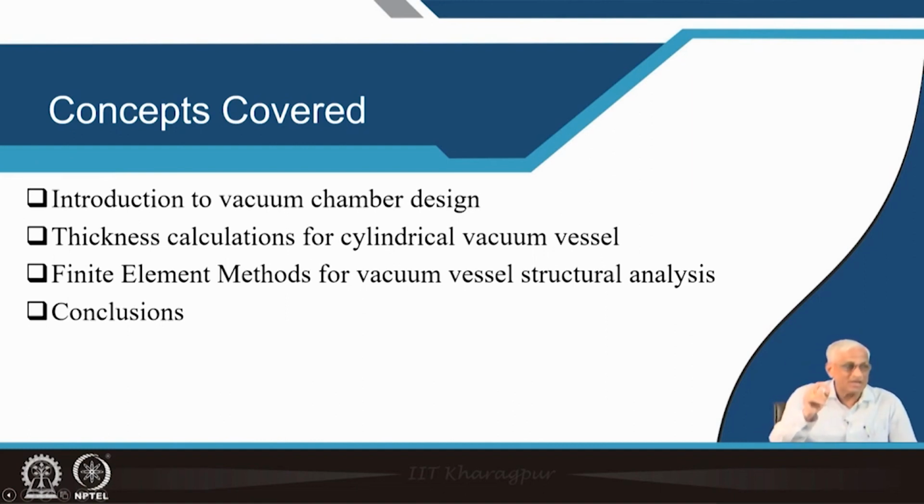So if the material is not properly polished, the molecules, particularly in molecular flow situations and ultra high vacuum conditions, are exposed to a very large surface area because they can go into the internal micro cavities because of roughness. So that is also very important in chamber manufacturing. So thickness calculation and some thermal issues, and finally the surface finish. All these things should be decided before you take up the fabrication of a vacuum chamber.